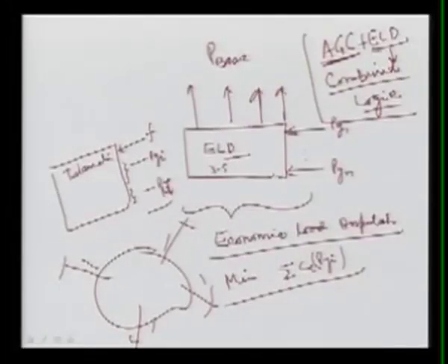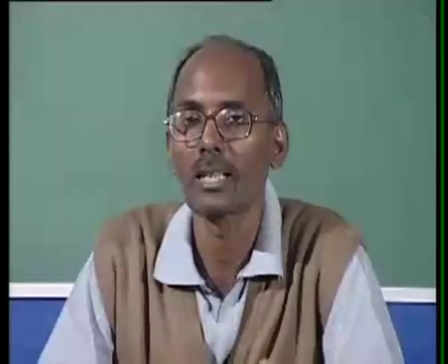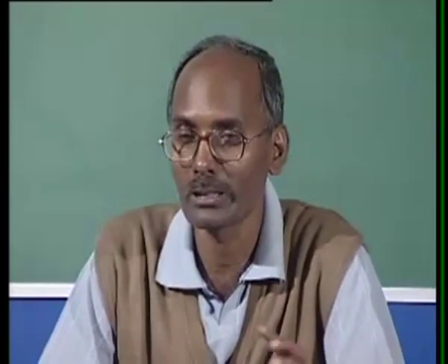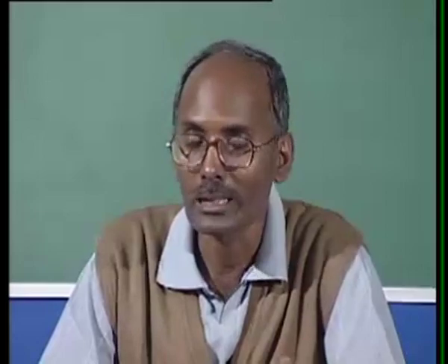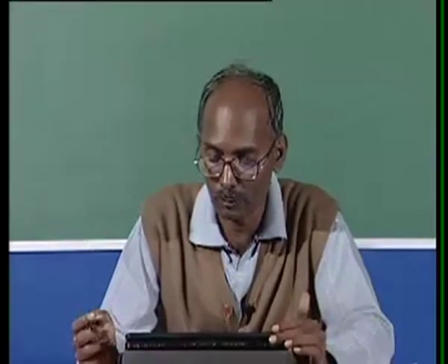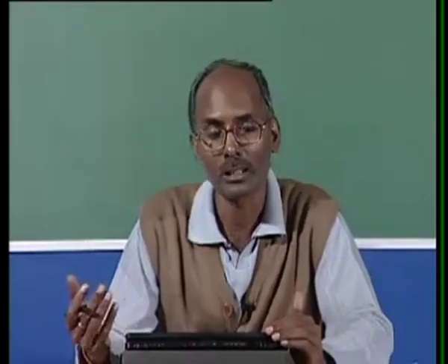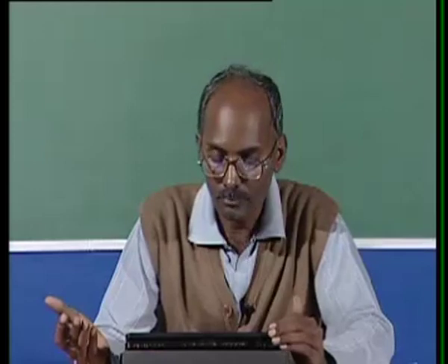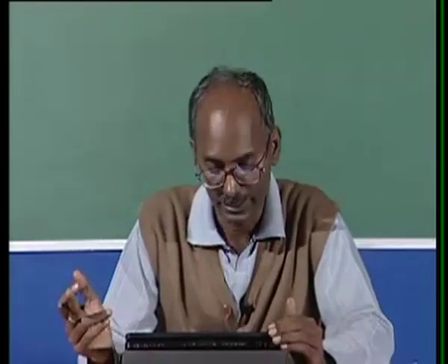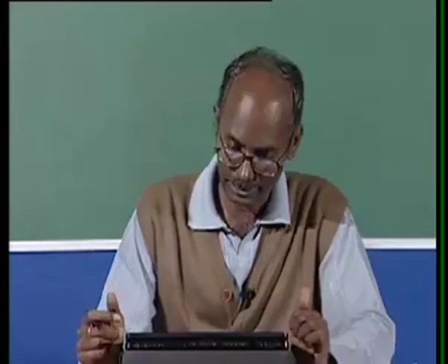Here, other than this economic load dispatch, there is another one called optimal reactive power dispatch, and that optimal reactive power dispatch is changing the voltage, or you can say the reactive power generation, thereby we are changing voltage, and the system losses and the injections are different. And then we'll say there is another loop, that is your voltage control loop of the alternator, we'll discuss in our next lecture of the same module.